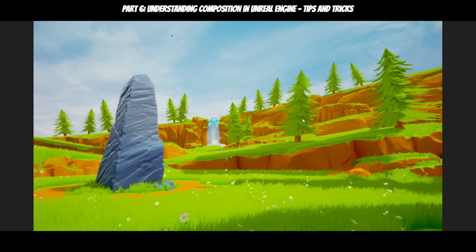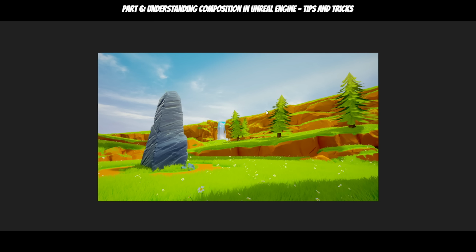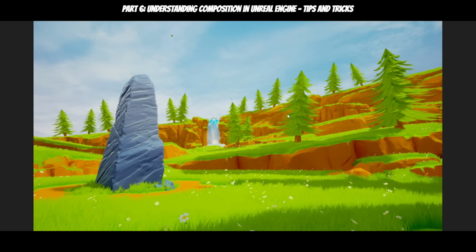This next one is a more finalized look, as you can see. So the trees are at their final position, and I've already fixed their normals. So you can see here we have the black back faces that we don't want. So we have more smooth back faces over here.